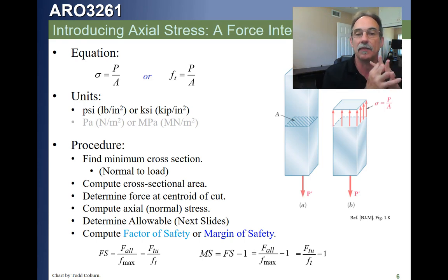Factor of safety is used commonly in civil and mechanical engineering. In aerospace, we typically bury the factors of safety in the loads. There are requirements for what the factor of safety is in aerospace. Usually it's 1.5 for most aircraft, helicopters, and those kinds of analyses. So we'll take the max loads we'd ever see, which we call the limit loads, multiply them by the prescribed factor of safety, which is generally 1.5, and that gives us a new set of loads, and we generally analyze to those.